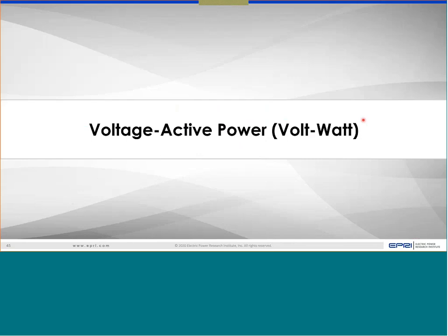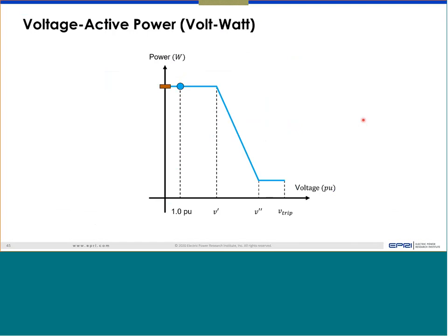So far, the two functions are both reactive power based support functions. Now this is the only one where you're actually touching the active power. And remember that since it's active power, it's more sensitive than reactive power, because any reduction in active power will have a direct impact on the revenue for the customer or whoever is owning the DER plant. So that's why it's very sensitive, and its use also needs some thinking beforehand. But first, let's discuss the actual behavior.